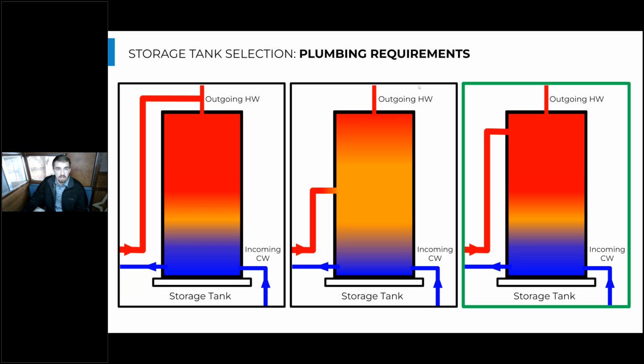So the second thing I've seen here is utilizing more typical connection locations on a standard tank and supplying this hot water from the heat pump right to the middle of the tank. And that will work in most cases when the tank's fully charged, because our goal, remember, is to have hot water on the top and cold water on the bottom, like we see here. So if this tank is fully charged with hot water, we're dumping this hot water into the hot water portion of this tank, so we're good there.